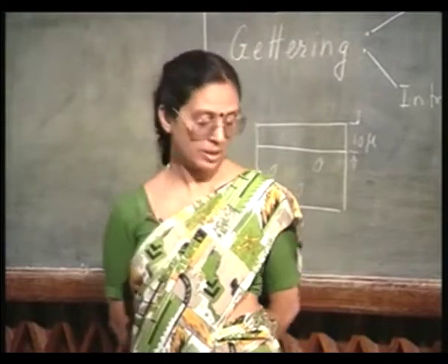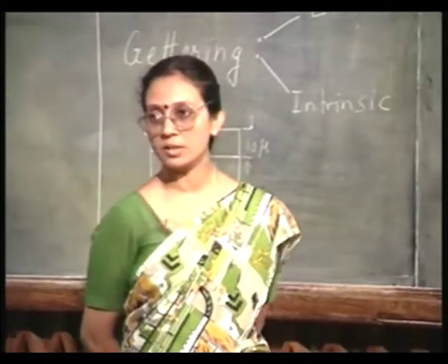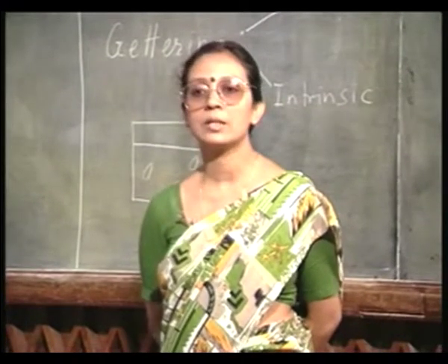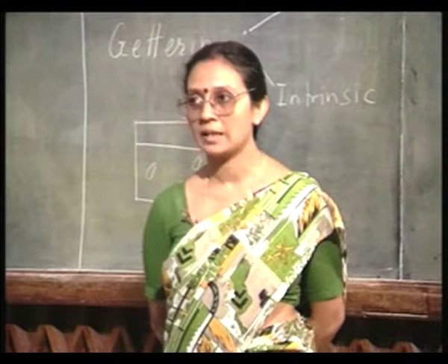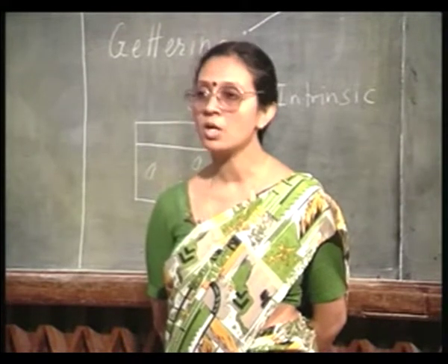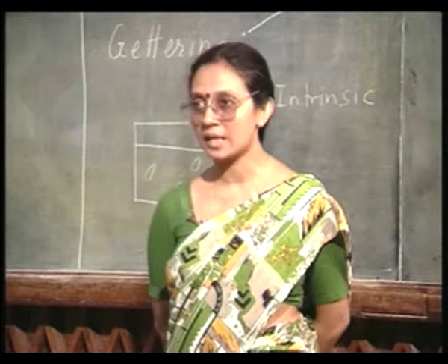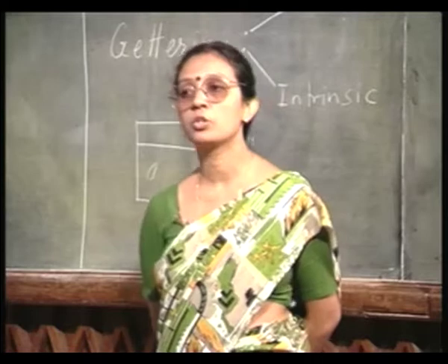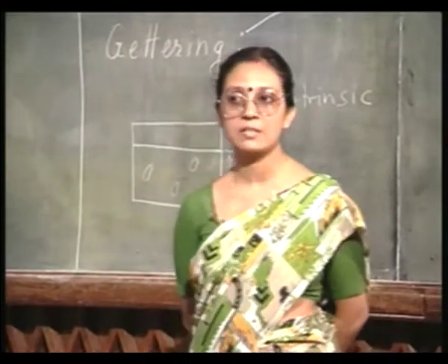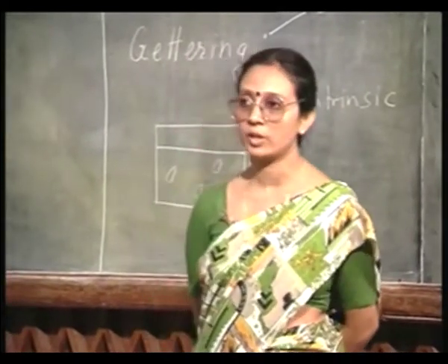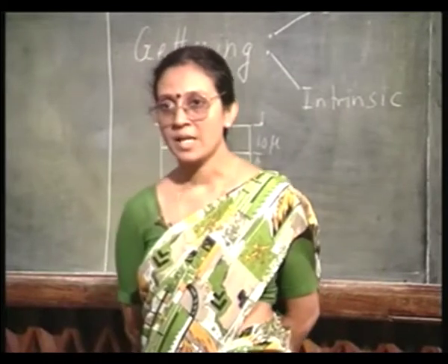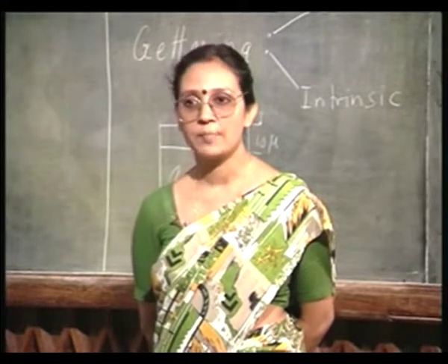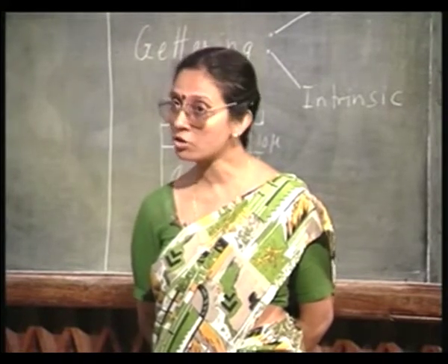For example, think about your bipolar junction transistor. In order to make an NPN transistor, we started out with a p-type substrate, and then after the buried layer diffusion, we had to carry out an epitaxy in order to have the N region grown on top of the p-type bulk crystal, and the actual device was housed in this epitaxial portion, not in the bulk crystal.